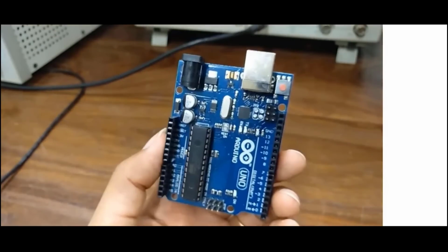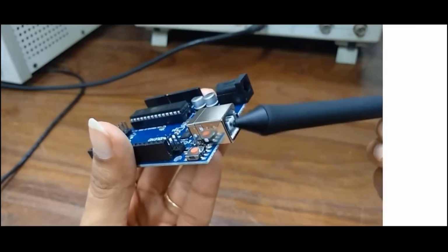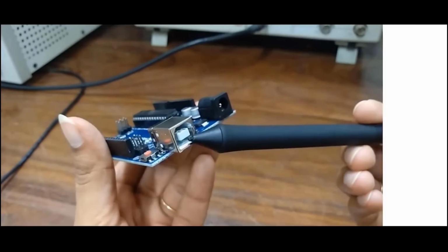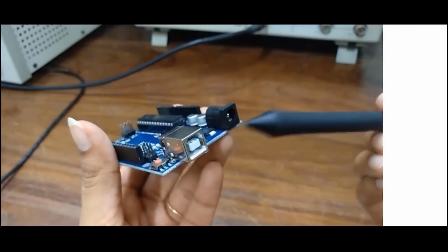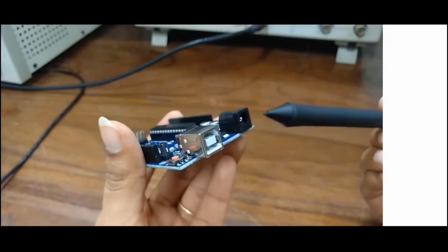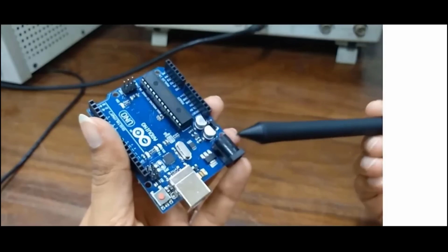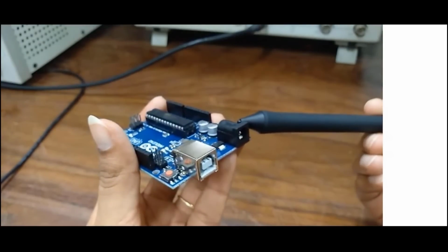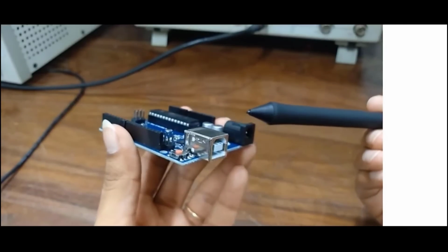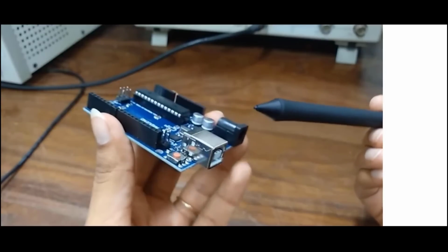Now, how do we load any program onto this board? This is the USB port, USB type B. So we use a USB cable. One side is type B that goes into the board, and the other side is type A, which goes into the laptop. Here we have the power port. The recommended input voltage for Arduino Uno is 7 to 12 volts, and you can connect a DC power source or any battery to this power pin. However, since a laptop USB can also provide about 5 volts, in this experiment we can use that instead of connecting a DC power source or a battery separately.